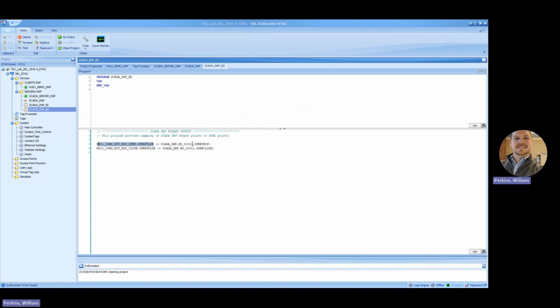You can also see that within that binary output point, or that control point, the SCADA has just one point. It's 0.001. But because of the control, they can send an oper trip and they can send an oper close, which then gets mapped directly over to your open or close of the 2411. So from the control center, they send an oper trip command coming into this program here. You can see that the oper trip is mapped directly to the RTU motor operated switch point, which then, using the IED DNP data map, gets sent to the 2411, which then utilizes the logic diagrams to send a control directly to OUT101, which will open the switch.